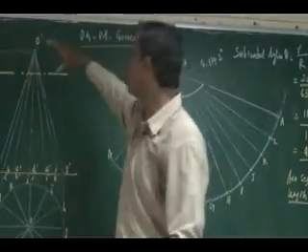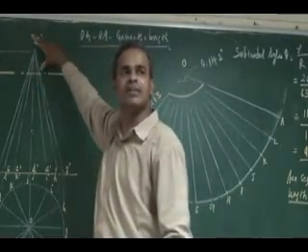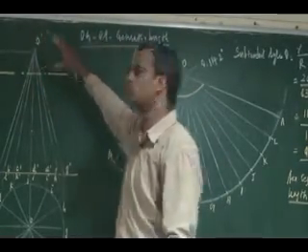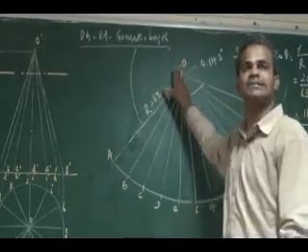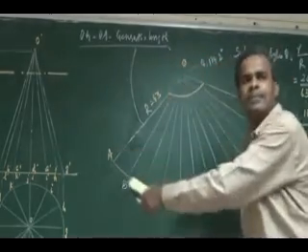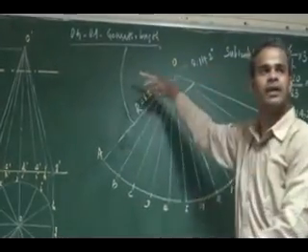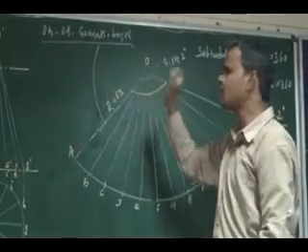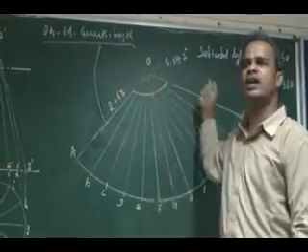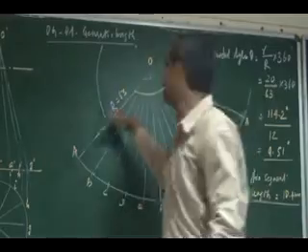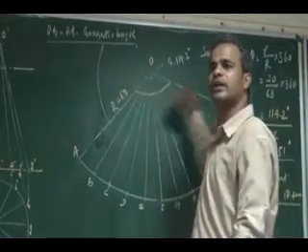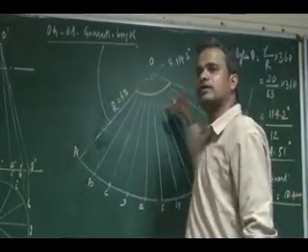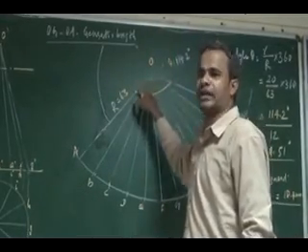For that smaller cone, you measure the generator length from your front view. Using that in your compass, you directly cut an arc similar to the bigger cone. That is nothing but my first cutting points. You need not mark cutting points or transfer them. Just show it as an arc, something like a smaller cone you generate.